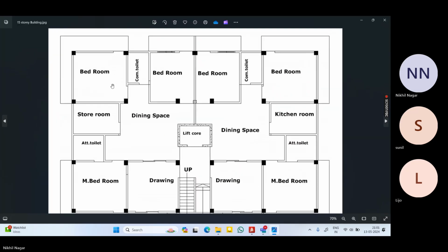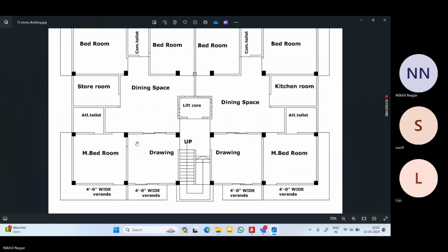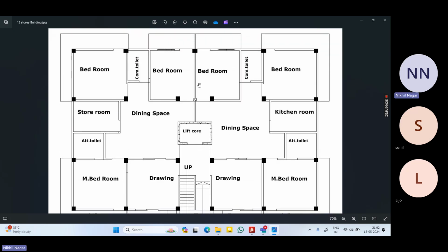This one. So for the bedroom, 1, 2, 3, 4, and bedroom, it is also a bedroom, 5, 6. Okay, 1, 2, 3, 4, 5, 6. So we have to make 6 plates having the same live load according to our IS 875 part 2. These plates should have the same live load because the room type is the same for these 6 rooms. Okay, first, second, third, fourth, fifth, and sixth. So I make the plate for these rooms first.